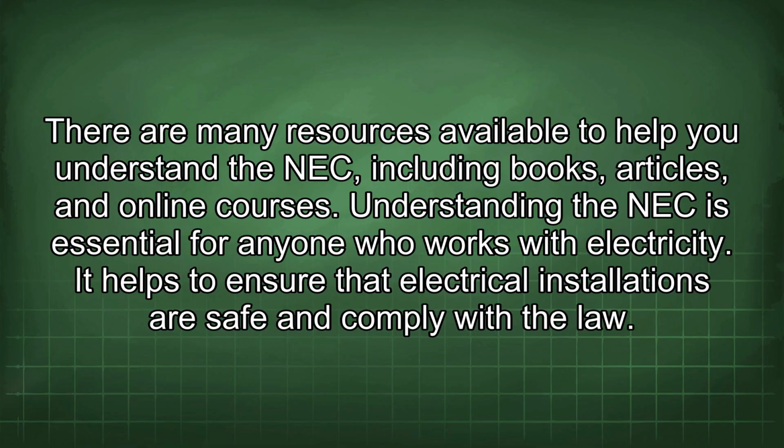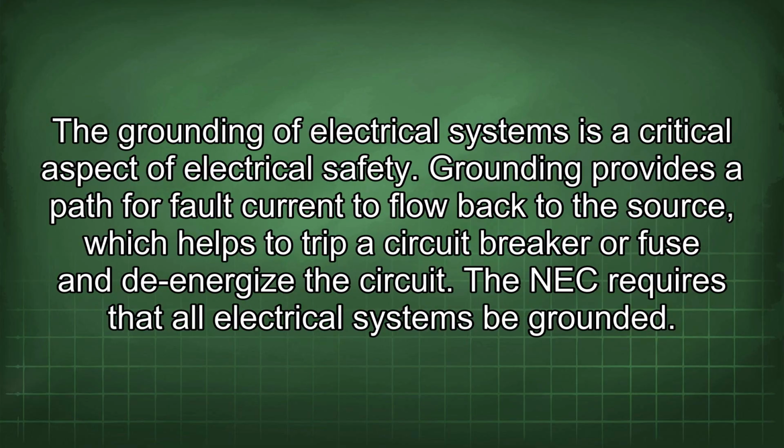Understanding the NEC is essential for anyone who works with electricity. It helps to ensure that electrical installations are safe and comply with the law. The grounding of electrical systems is a critical aspect of electrical safety. Grounding provides a path for fault current to flow back to the source, which helps to trip a circuit breaker or fuse and de-energize the circuit.